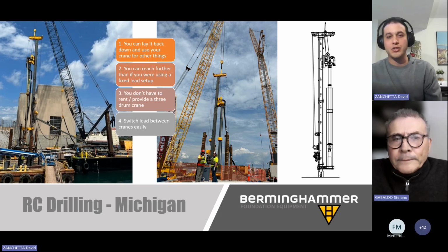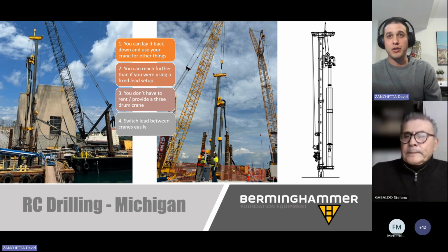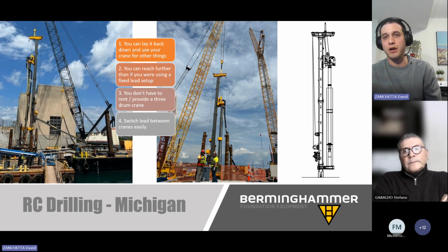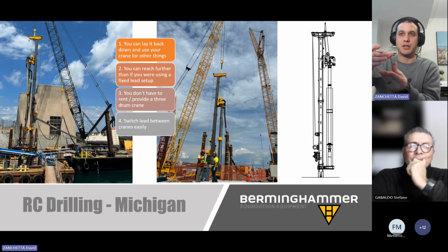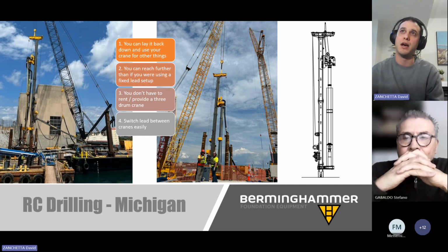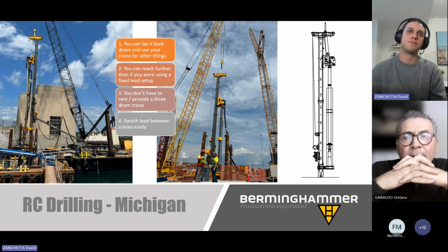Okay. Traditionally, depending on the length of the lead, we have a number of what we call tool following gates. Those gates are suspended from the head shifts at the top of the lead on one end and essentially follow down the lead so that they can brace the auger at 2 or 3 points that are always slowly decreasing down till they're right at the bottom of the lead. I don't know, Steph, if you wanted to add anything to that.